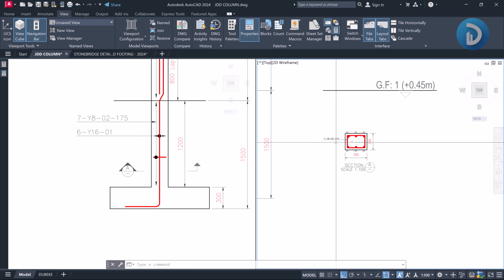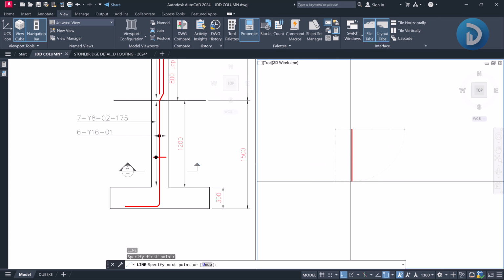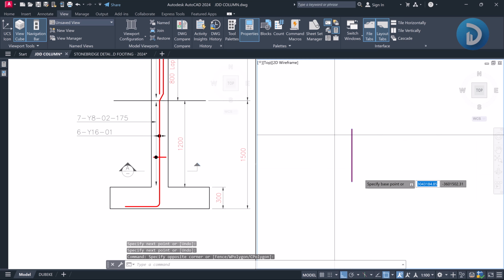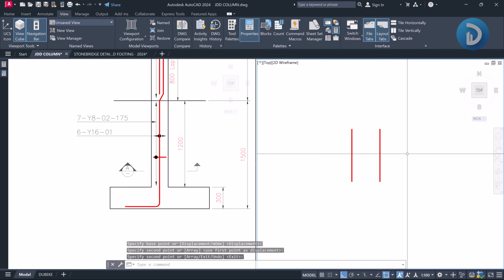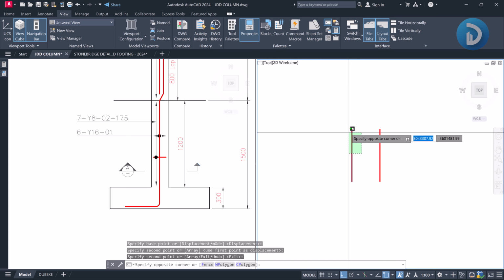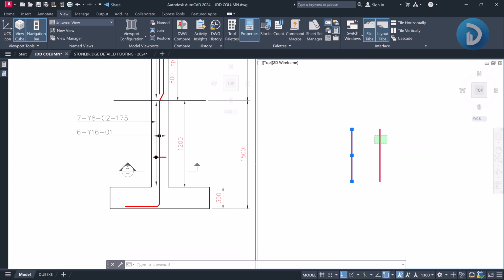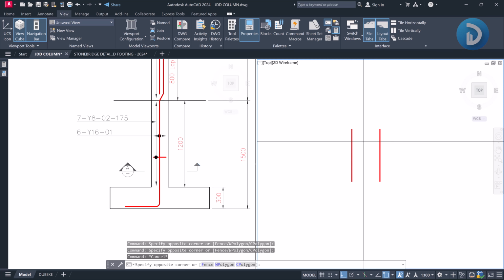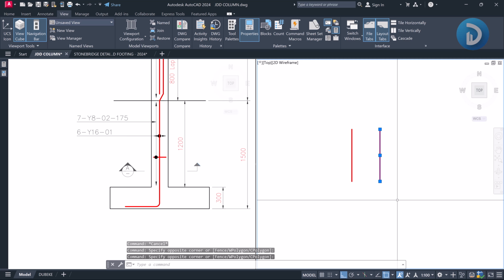All right, and we said there are some basic rules that guide this bar mark. If we have a reinforcement of this length, and a different reinforcement having this same length, but the diameter of this reinforcement is 16 millimeter, while the diameter of this one is 20 millimeter, it means they will have different bar marks.